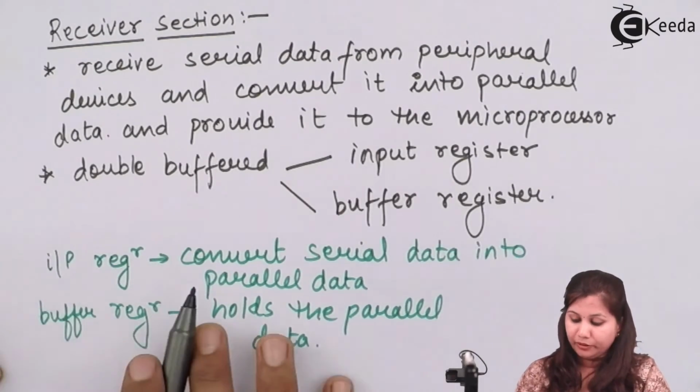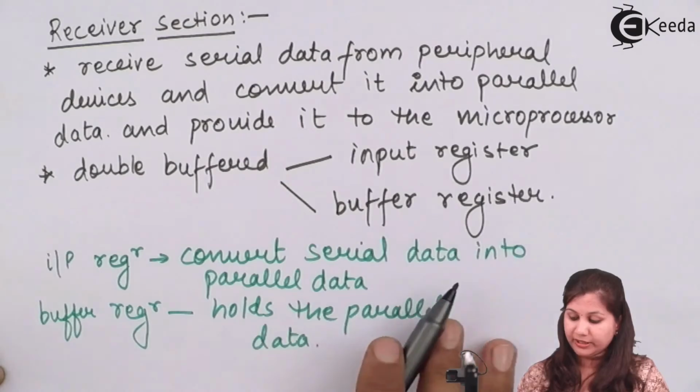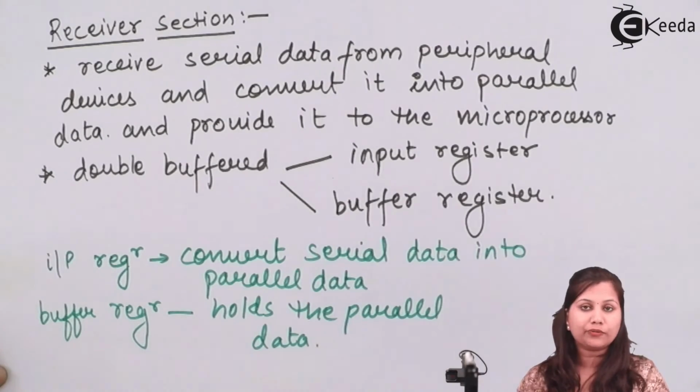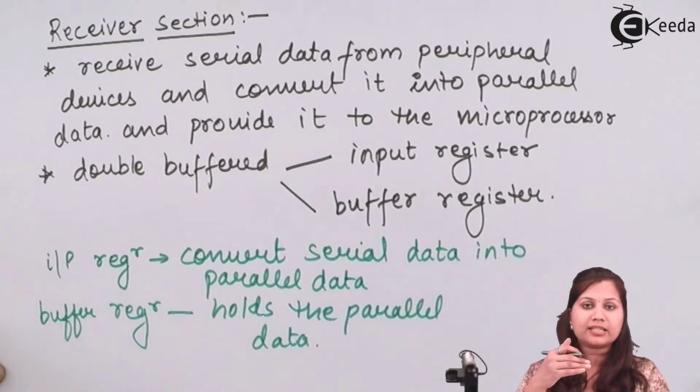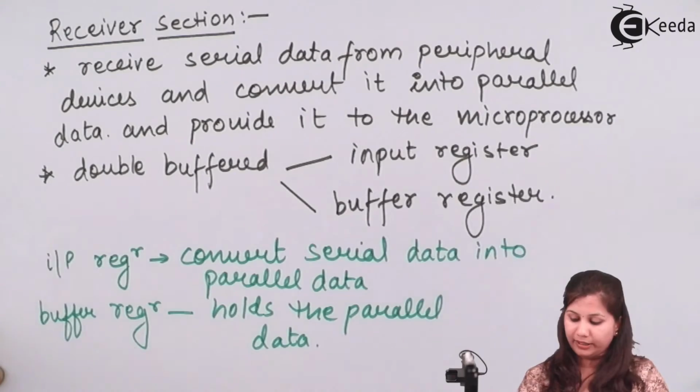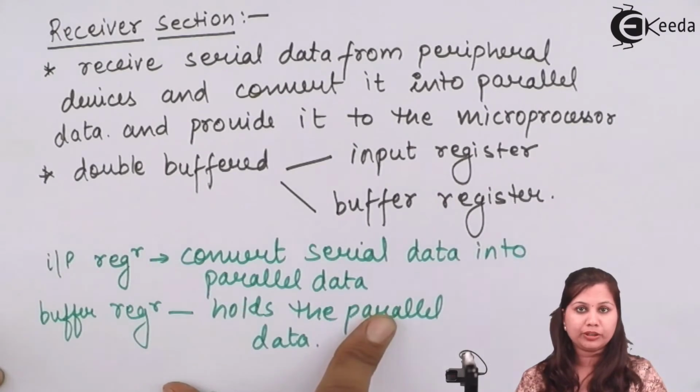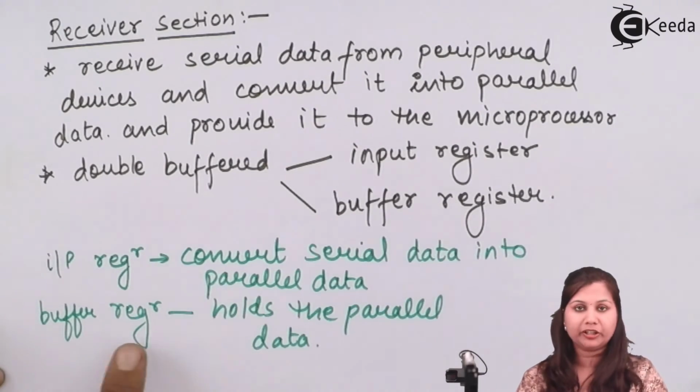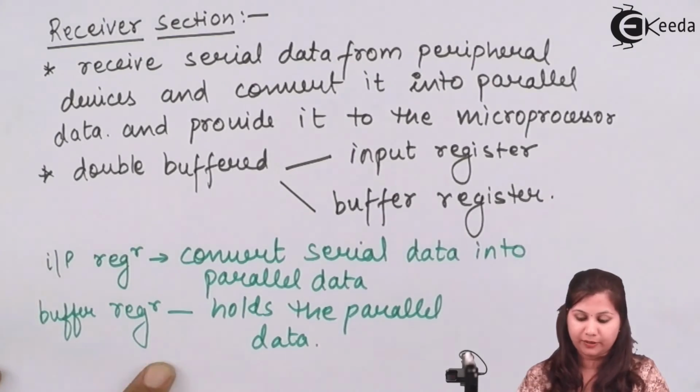First it receives the bits from the peripheral devices. Whatever the first bit is, the 8251 treats it as the start bit of the data. After that start bit, whatever bits it gets are considered data, converted into parallel form, and stored in the buffer register.